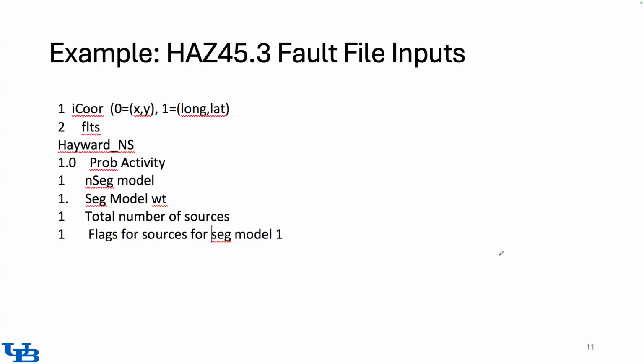So you can assign a probability of 0.5 for one realization of the Hayward fault and define its geometry, and also assign the probability of 0.5 for the second definition of its geometry. So this is to allow you to essentially account for the same fault, to define the same fault more than once, to account for any epistemic uncertainty that may be coming from that.